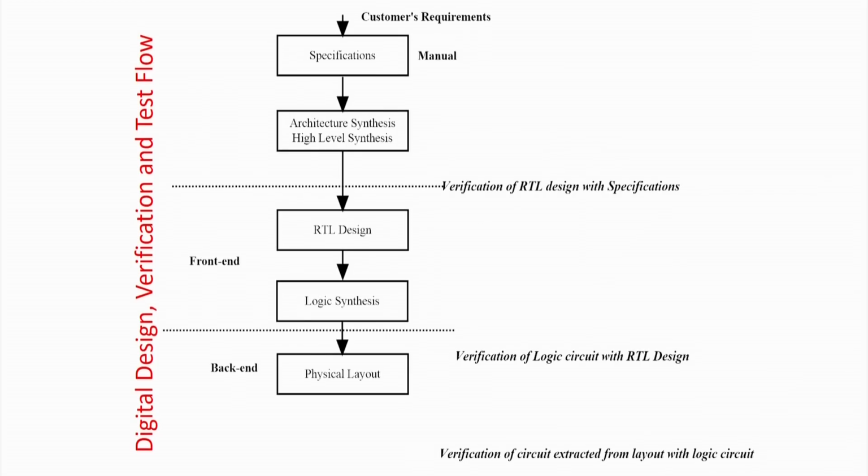And finally when your chips are out in the market, you have to test them physically, so that you do not by chance ship some defective parts. So what can be the optimization techniques here? Of course the CAD tool which generates the test patterns should be extremely fast, and the good quality test patterns should also be such that they do not take too much time to test, so that you can test more physical devices in a lower amount of time. Now we will go into more depth of the introductory part.